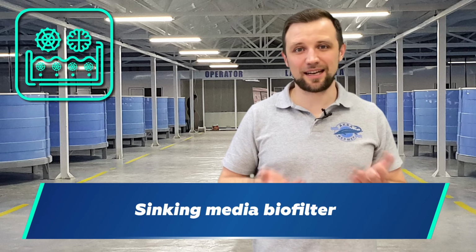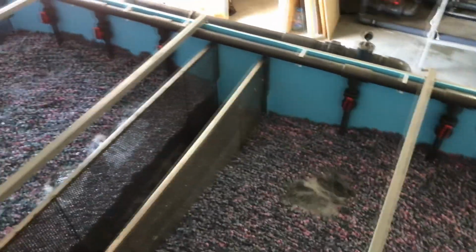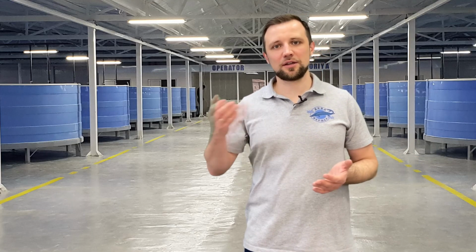Biofilter operating on sinking media. What is it for? It's very simple. There are small impurities that are not detained by the drum filter, as well as dead biofilm from the moving bed biofilter. So, the sinking media biofilter traps all these fine substances as the water passes through a layer of static media. In this way, you can achieve higher water quality and its maximum transparency.